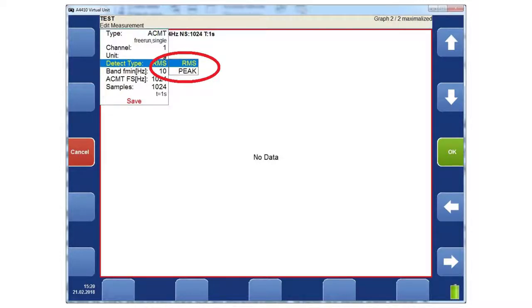I work rather with RMS values because it enables good trending in time. The RMS is much more stable than true peak. It is clear that when I select RMS compression, then the peaks in the signal will be lower than peaks in the original signal. It is the mathematical rule.